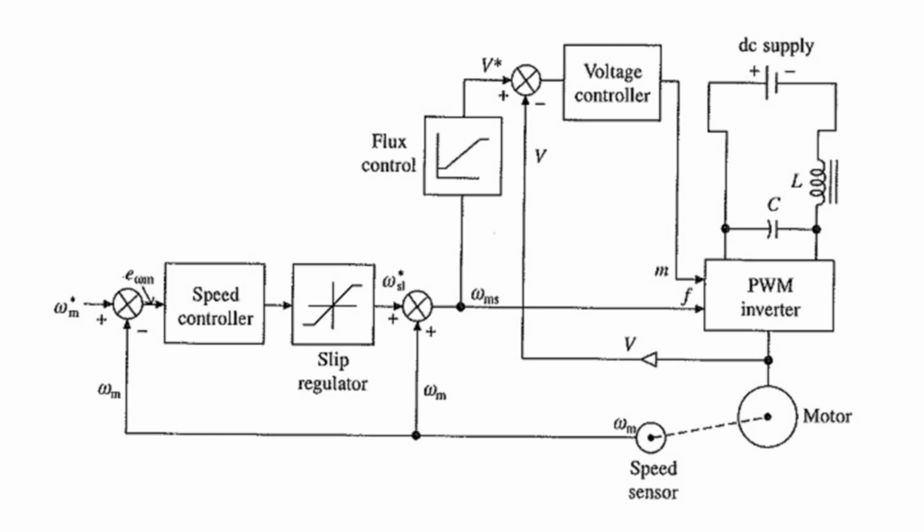The maximum value of this is limited to the maximum permissible inverter current, for the positive side as well as the negative side. The slip regulator sets the maximum permissible value, and you get the synchronous speed.